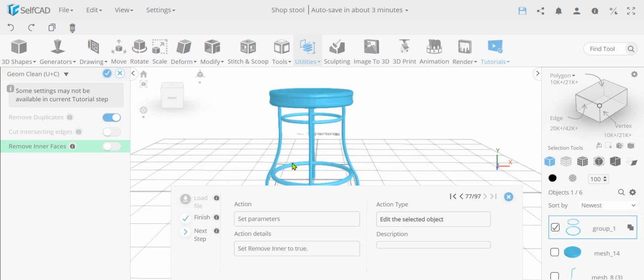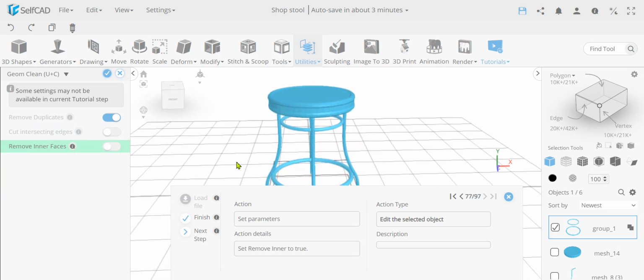In this case, you cannot remove duplicates yet, because they have faces, so they actually belong to each other, because each one needs to represent its own faces. So you need to remove the inner faces. In the order of operation, you first need to remove the inner faces. After you remove the inner faces, you will still be left with the duplicate vertices. Then you can remove duplicate vertices.